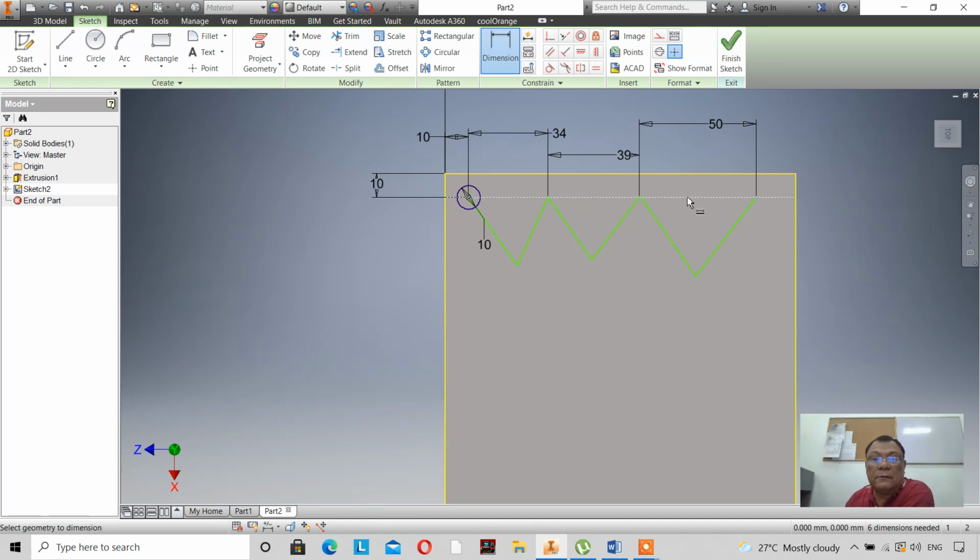I will use the rectangular pattern tool from this hole, have this one there, and there, and the distances are different. I will use now the equal tool of this and this. Okay? Equal this and that.